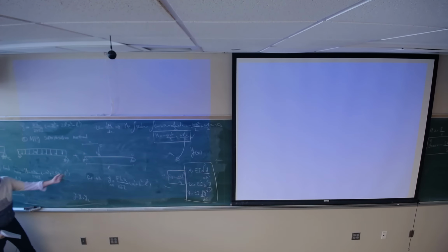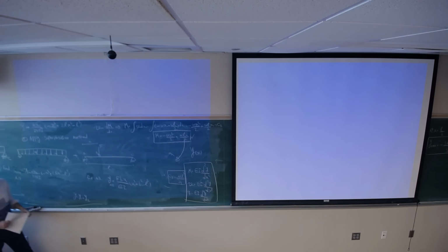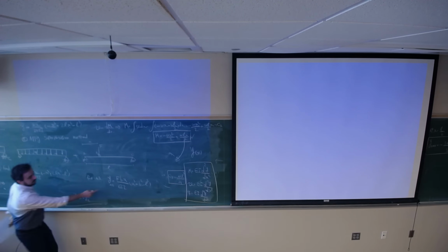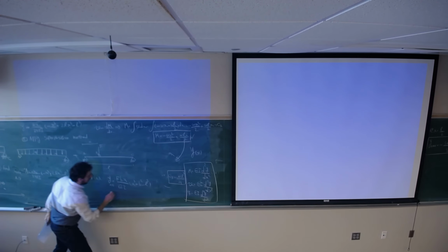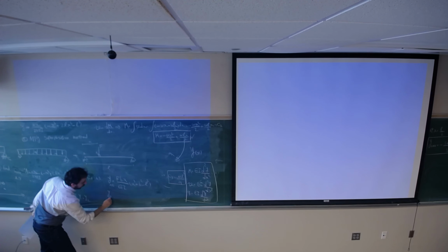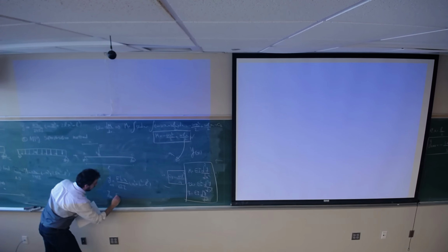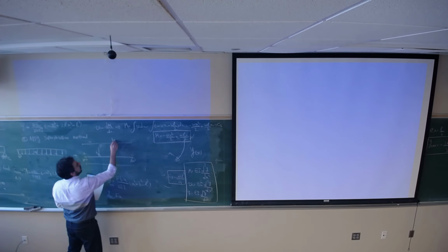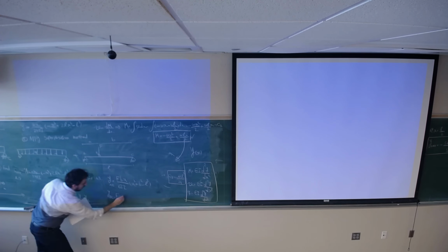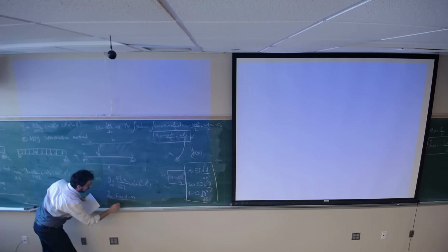If you are looking for deflection for section AB, any x between A and B, you should use this equation, minus. And for section BC, it is going to be F times the distance of A, L minus x, divided by 6EI.